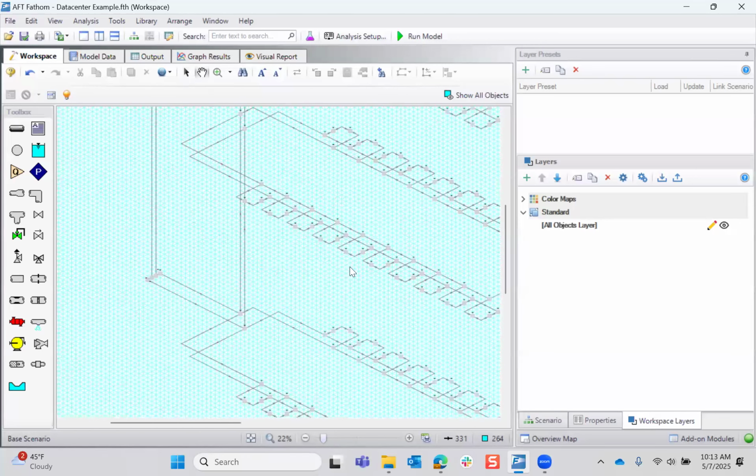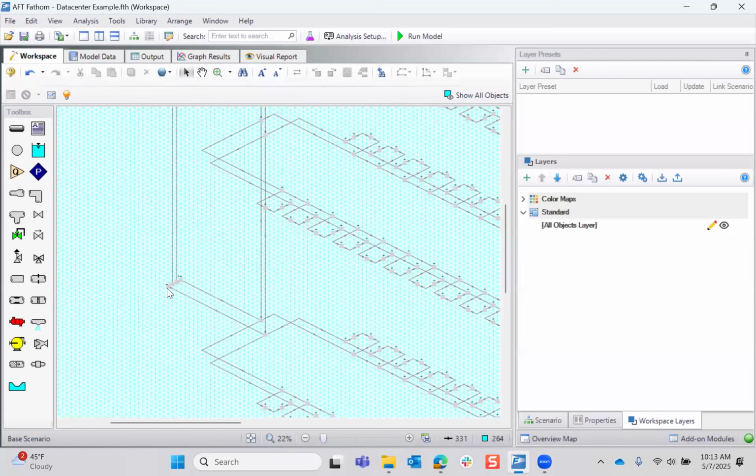Well, technically speaking, this control system should just push my pump back on its curve until it's a balanced solution. But I didn't really like that sort of solution. It would mean having my pump potentially operate way too far back on its curve, which can cause efficiency problems, have your pumps break down more frequently, downtime on the cooling system, those sorts of problems.